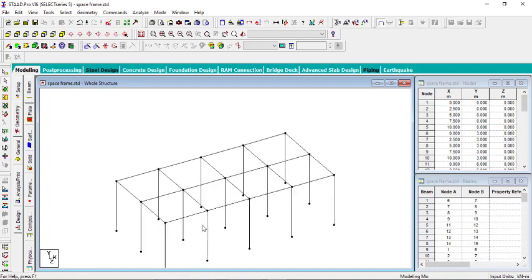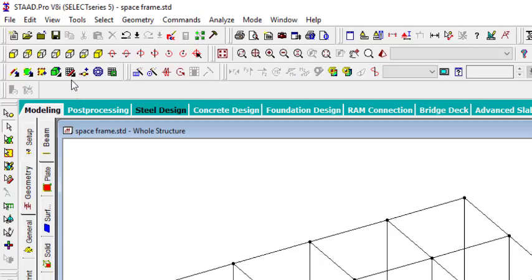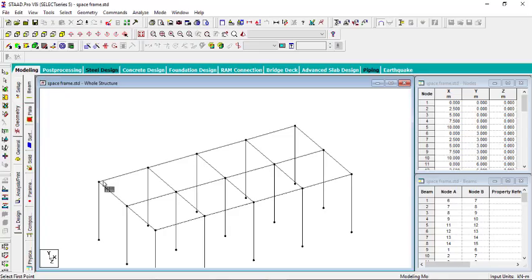Okay. Now I'm going to draw a slab. Now this is the slab I'm going to draw. I am going to use this one. I'm going to generate a surface mesh. So to do that, you click from this point up to this point, up to this point, up to this point, and then you're going to click the first point.